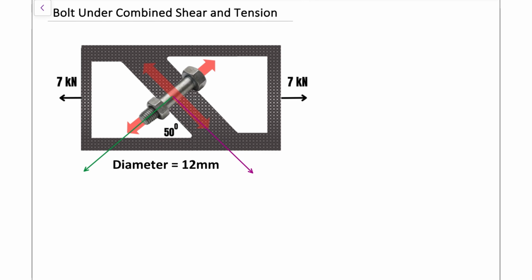And what that will look like, if we were to think of this as a triangle, and if I just close that side there to create a triangle, then that horizontal side that I've just drawn will be representing our hypotenuse. And where the direct and the shear force meet, right there we'll end up having a 90 degrees. So it means then that our 7 kilonewtons will be our hypotenuse.